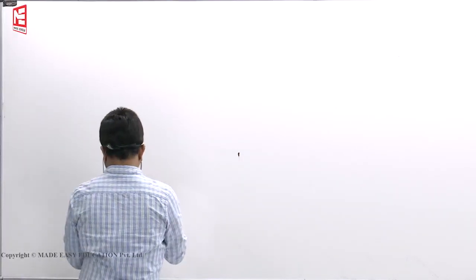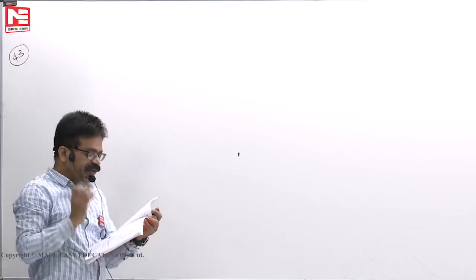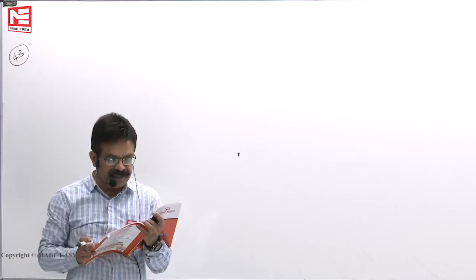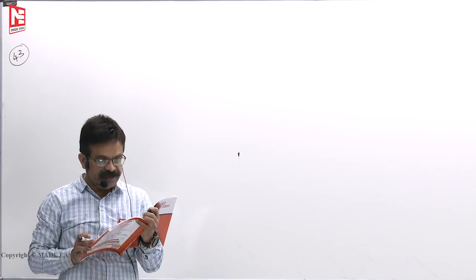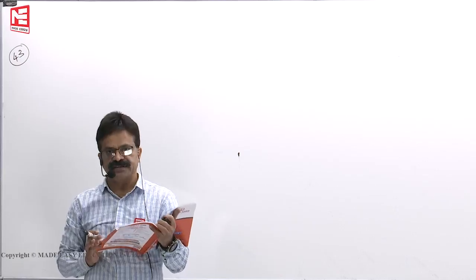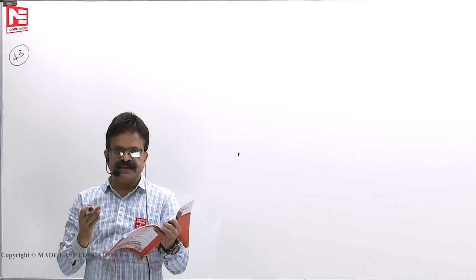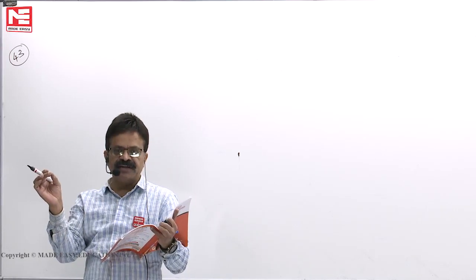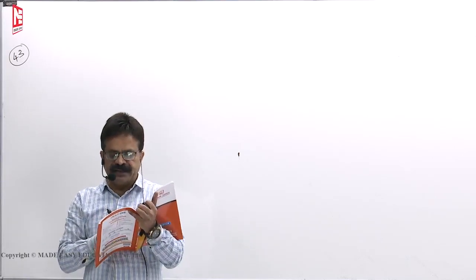Okay. Now we'll see the 43rd question. Any arch cannot practically be built to the shape of the theoretical arch. Correct. Why? The shape of the theoretical arch is affected by the loads moving on it. Reason is also correct. If the loads are moving, the shape of the bending moment diagram changes. That means once you build one theoretical arch, when the loads move, bending moment changes, but the shape of the arch will not change. That means that you cannot practice.